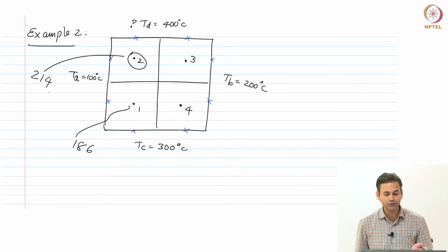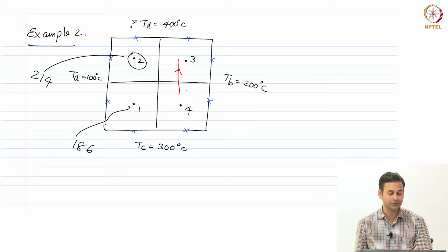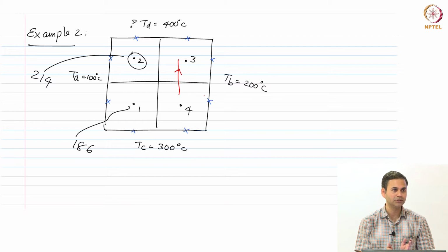It is kind of higher because you have a higher value on the upper temperature. You will use these values as the guesses instead of 100, 100 for T1, T2 and then do the same TDMA here. Then you come back again to T1, T2 and keep iterating until you reach a converged solution. Would you be able to do T3, T4 and continue this process?